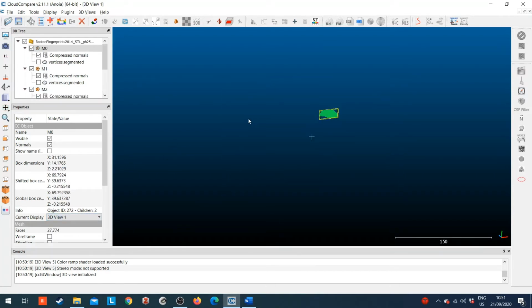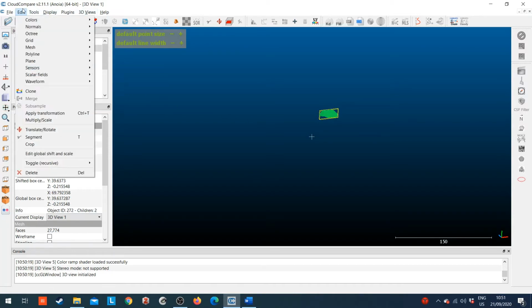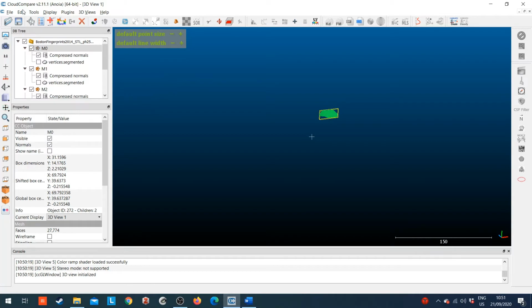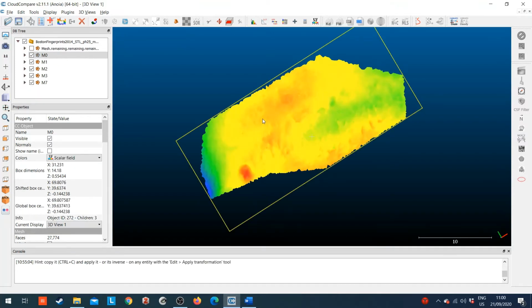Great. After you've got each of the individual fingerprints isolated on different 3D views, we want to make sure that these meshes are uniformly flat, as we did in exercise 3. I tend to use the fit to plane option under edit, just so that the software identifies what is considered level for these fingerprints, but you can use either method. So you should have aligned each of the meshes and exported their aligned Z coordinates using the export coordinates to SF option for each of the fingerprints.